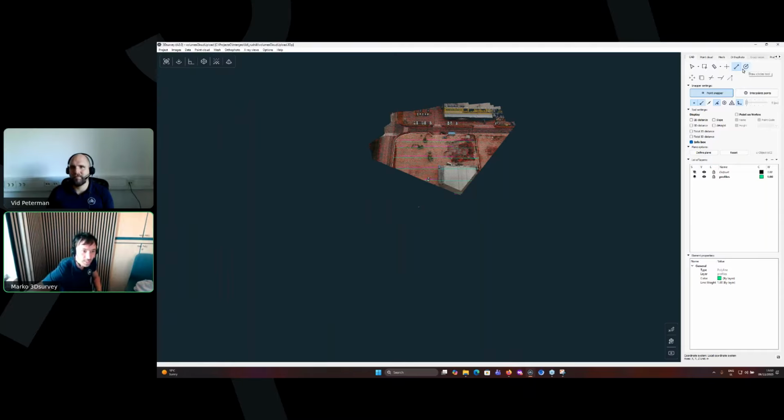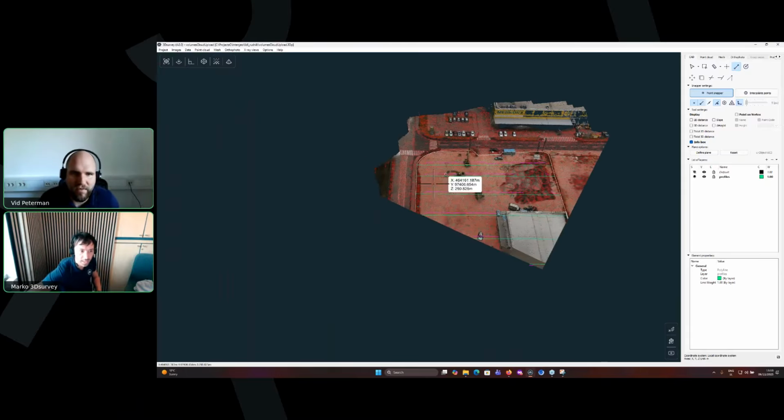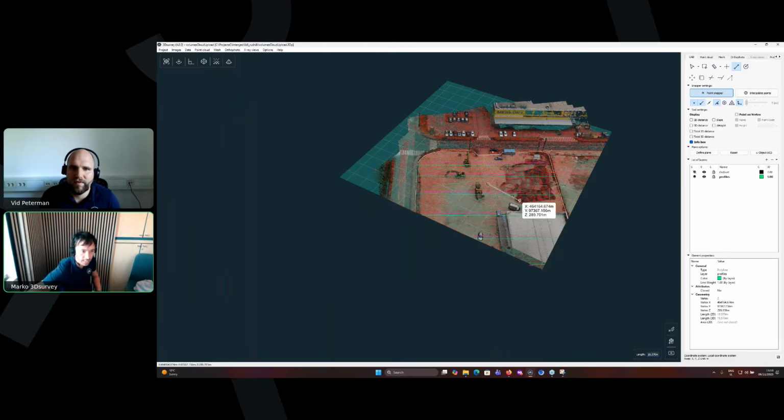So you have a circle option, but not with 3 points, okay? And a rectangle, you can draw it, but you have to draw it slowly with the regular line. So if I go in here, I draw the first line and then I enable UCS. If I were on a plane, everything would be perpendicular to that first line. Because we are doing everything in 3D, it's a bit different, okay? In some cases, it's difficult in comparison to, let's say, just 2D AutoCAD. But with a combination of functions, you can do this easily.